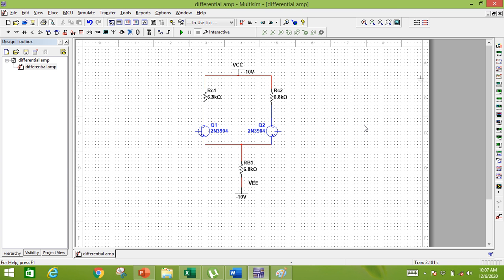We know that operational amplifiers have two input terminals and one output terminal. One of the most important qualities of an operational amplifier is that it amplifies only the difference between its two input signals, while rejecting or severely attenuating signals common to both the inputs. This allows operational amplifiers to be used in systems where a large amount of electrical noise is present. So in this case, the desired signal is amplified while the noise common to both the inputs is attenuated.